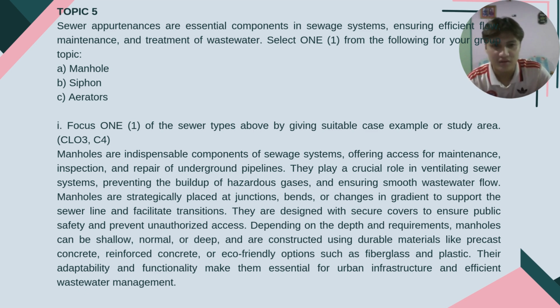They are designed with secure covers to ensure public safety and prevent unauthorized access. Depending on the depth and environment, manholes can be shallow, normal, or deep, and are constructed using durable materials like precast concrete, reinforced concrete, or eco-friendly options such as fiberglass and plastic. Their adaptability and functionality make them essential for urban infrastructure and efficient wastewater management.